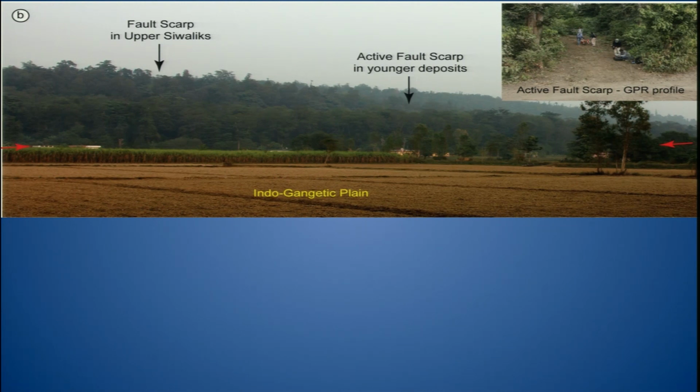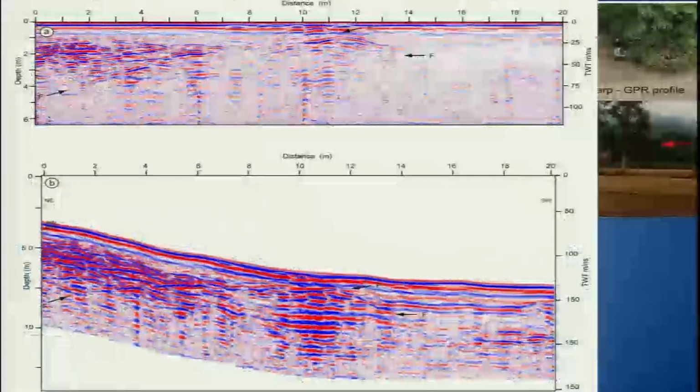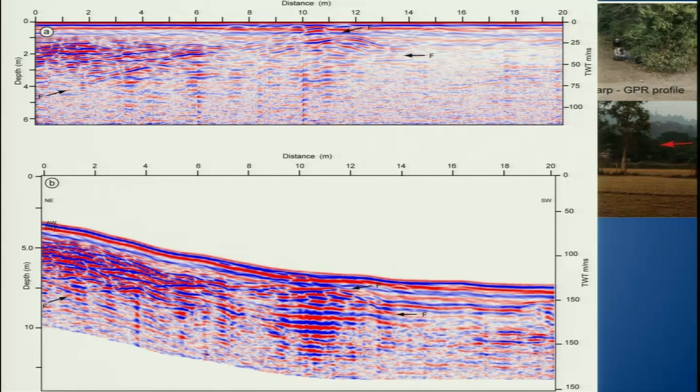We identified the appropriate area, and before getting into the trenching part, we did a GPR survey, which helped us in fixing our trench boundaries. This was the GPR profile. I would say this is a raw profile, not processed at all. Further, we added topographic corrections to this, as well as slight processing. After processing, we clearly see the low angle fault cutting the deposits, the young deposits.